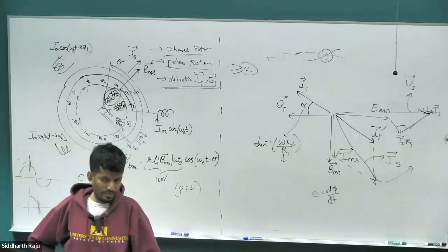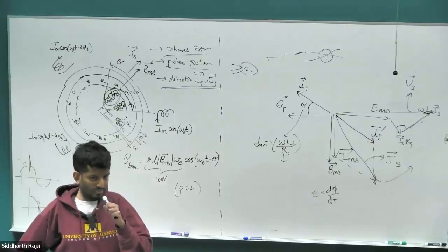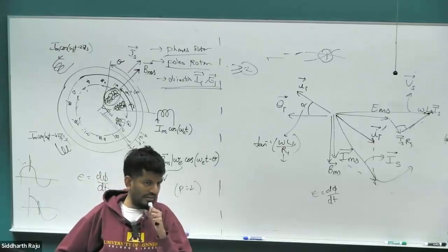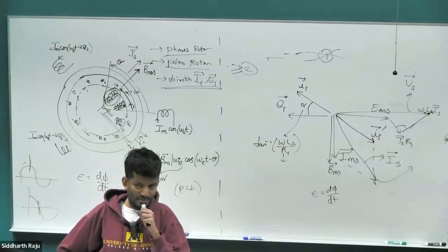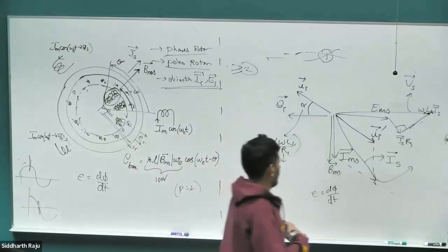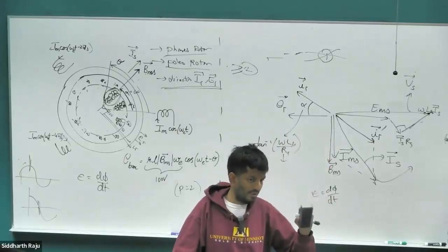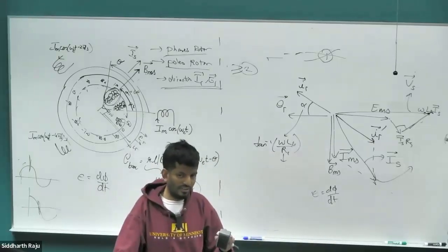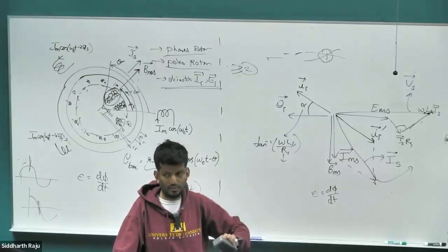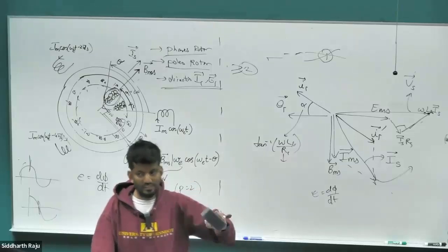When we use the circuit for a permanent magnet synchronous motor, what was the circuit called? The equivalent circuit. There was an added term prefix to it. So steady state, and per phase. So when we have a three-phase network, at steady state, you can just look at the currents of one particular phase and tell everything about the other two phases. So you can take a three-phase network and break it down into a single one-phase network at steady state alone.